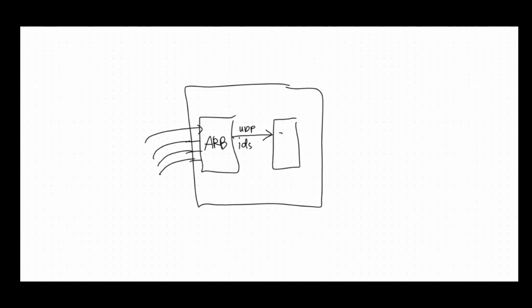So basically, incoming packets will enter our FPGA. They'll first be sent to the arbiter, which selects packets from these input ports and forwards them into the user data path, which we have set in our design as IDS, and it'll go into the IP router, which will send it out to where it needs to go.